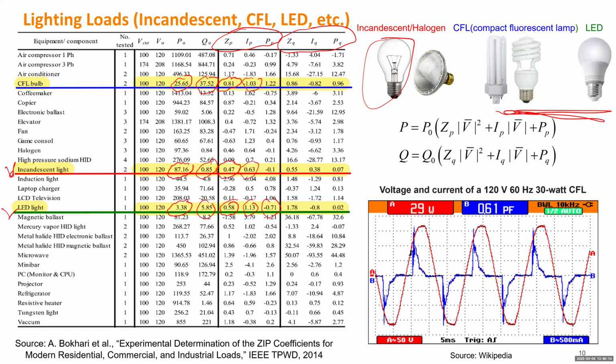To summarize, if we just draw the per unit value for current and voltage waveforms, and they look almost exactly the same, that's power factor 1. If they look different, that's not power factor 1. Different means they can have a different phase or a different shape. Those energy saving lights make the waveform of the current very different from a sinusoid. For this case, this is the peak value of voltage, and that's the peak value of the current. You have to do a Fourier transform to change this blue curve into different harmonics, from the fundamental to high order harmonics. First of all, the fundamental may have a phase shift, and they also have some other harmonics. So they will introduce reactive power. Reactive power is just a measurement of how different the voltage and current waveforms are. Any questions? All right.